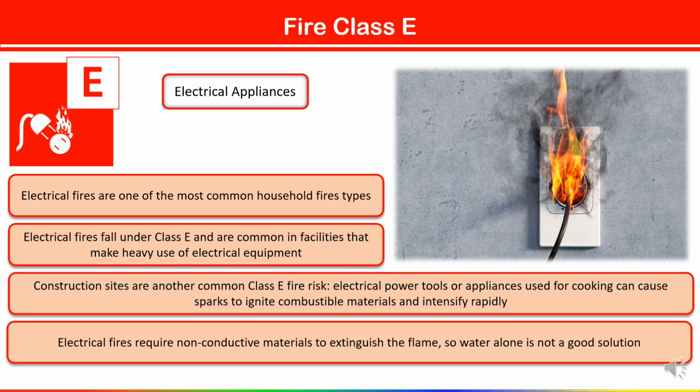You don't need to use water or foam, because water and foam are both conductive and can increase the risk of electrical shock, which could endanger anyone attempting to extinguish the fire. So never use water or foam.